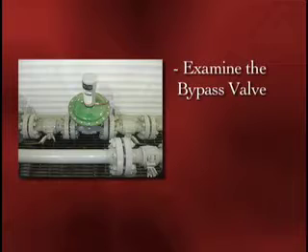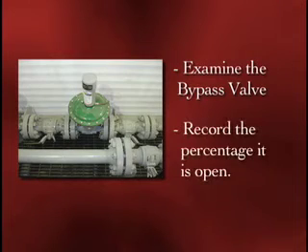Examine the bypass valve and record the percentage that it is open. On some units there is a digital or analog gauge, but if not, then an approximation of its position is fine based on visual inspection of the valve.